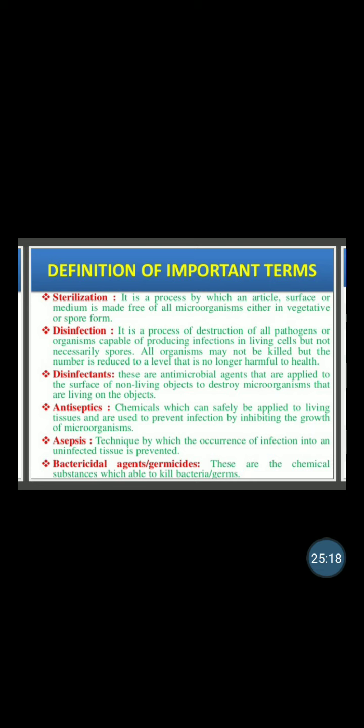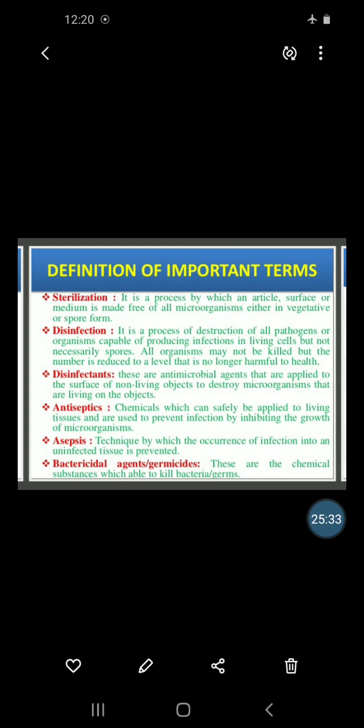But one note for this: first, the oven must be allowed to cool for about 1 hour before opening the doors, otherwise glasswares are likely to get cracked. Second, it should not be overloaded. Third, do not keep the material which will get decomposed at the operational temperature.